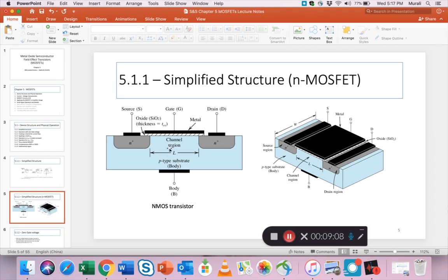But this p-type body, that means it's semiconductor silicon doped heavily with holes, right, with p-type, acceptor doping. It also has these two little parts of n-type doping. Okay, so these are donor-type doping. And one of these we call the source, which is on the left side, the other we call the drain. And the source and the drain are n plus, they are heavily n-type, and they have conducting leads that are brought out, terminals S and D.